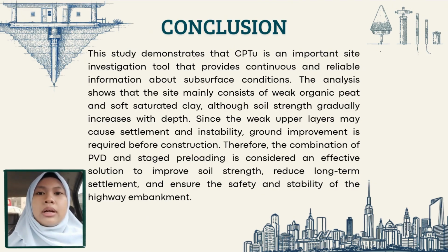Among the available ground improvement techniques, the combination of prefabricated vertical drains and stage preloading is considered suitable because it can accelerate consolidation, increase soil strength, and minimize long-term settlement. Overall, the application of CPTU data enables engineers to develop appropriate solutions and ensure the long-term stability and performance of civil engineering structures.